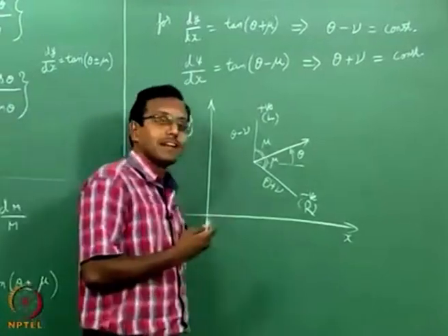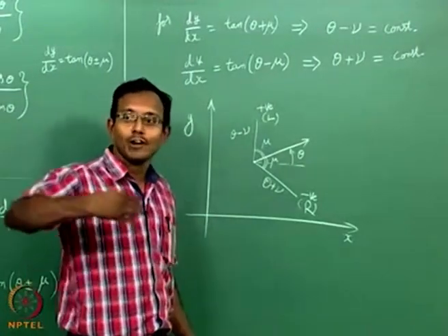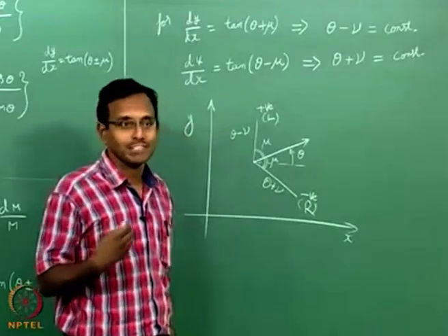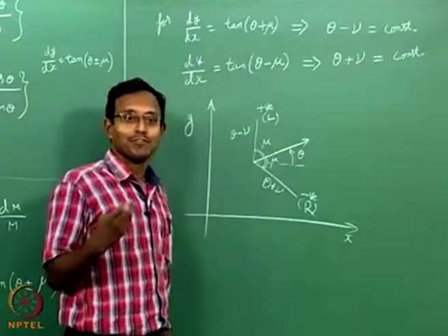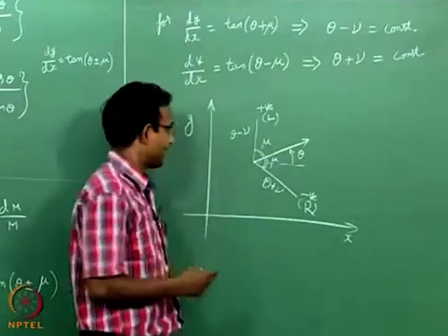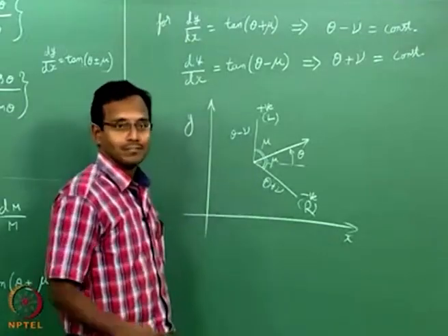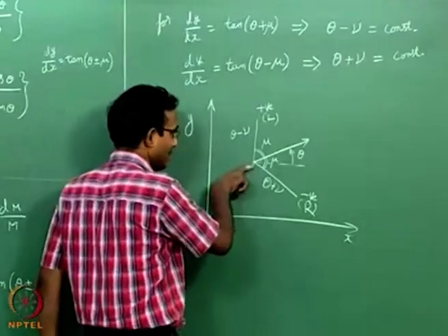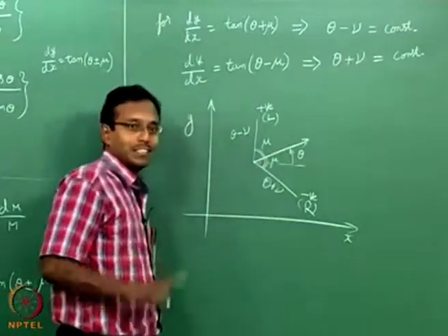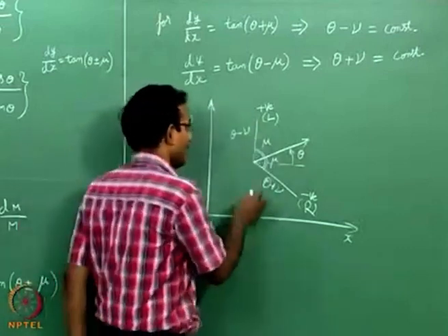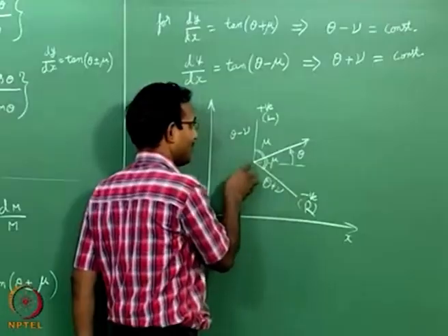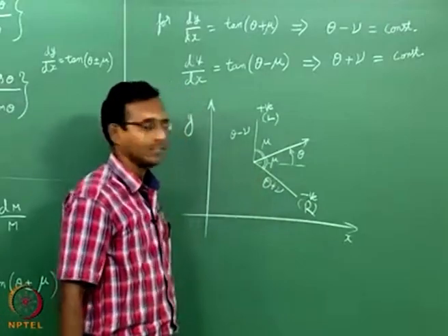So what is the connection between this and our already existing understanding of gas dynamics? If I think about it, now I have to give this connection of Mach cone and this. You have seen this picture before, where we are saying there is a fluid element that is going along this direction. There is a specific cone or a region inside which the flow will be having influence of this point, right?